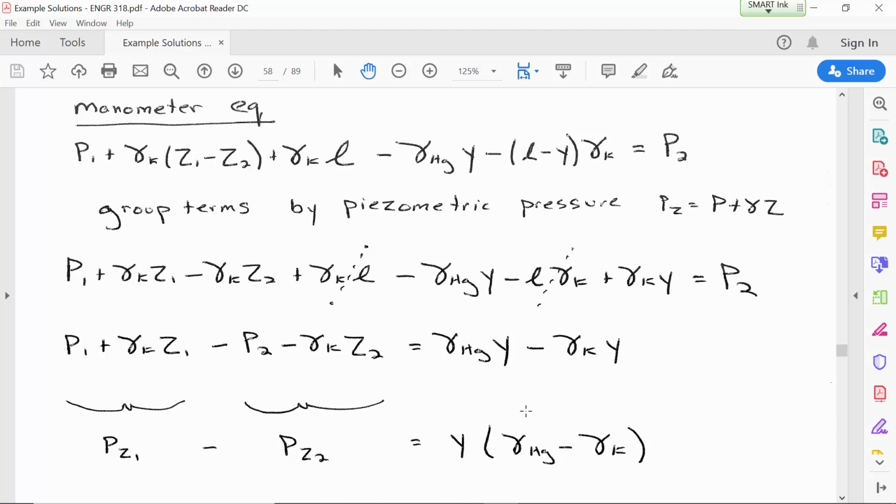Even though it's at a higher elevation, what the differential manometer is measuring is the pressure change that's due to pipe friction. So strictly speaking, it's measuring the change in piezometric pressure, not just the change in pressure. If it was measuring the change in pressure alone, then it wouldn't be level when the flow velocity was 0. But it is, and it only sets up a difference in elevation when the fluid is moving.